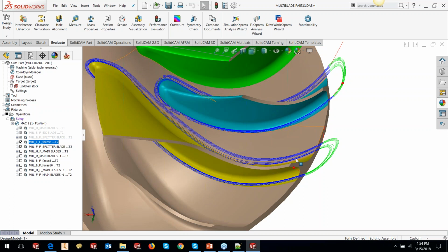And also remember that since you're going to run the fillet finishing, you can stop the hub finishing from the blade by 0.2, 0.3 away, so that when you're finishing the hub, your tool doesn't touch the splitter blades or the main blades. So you can just stop them much before, and the remaining portion of the finishing will be done by the fillet finishing itself, so we don't have to worry about matching and other things.